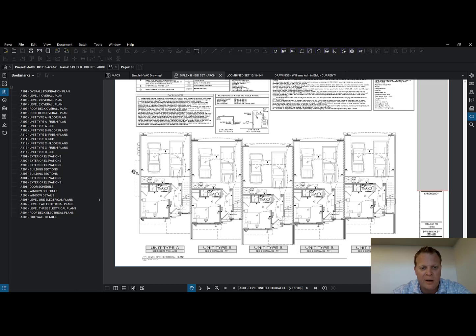How to route all that ductwork. We just covered ductwork, but how to route all the electrical main service, the gas main service, how to route the refrigerant. One of the challenges with refrigerant, and I highly recommend if you're going to do something like that, is picking one wall right here and not letting it get spaced out everywhere.